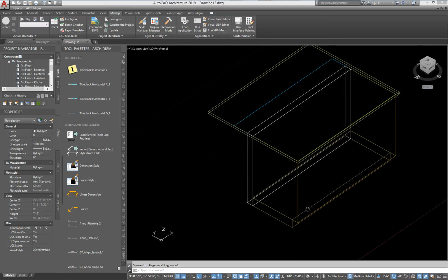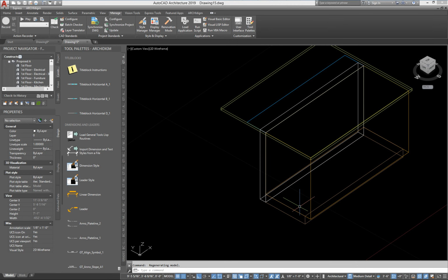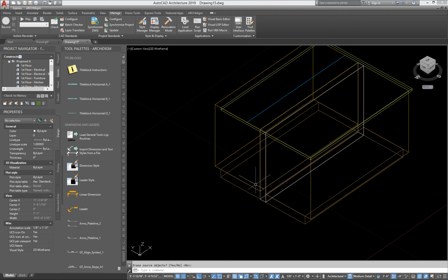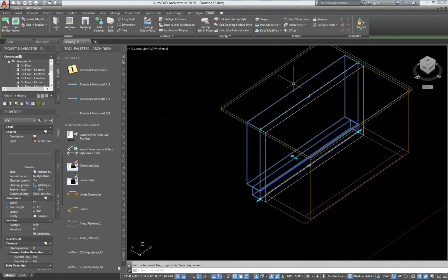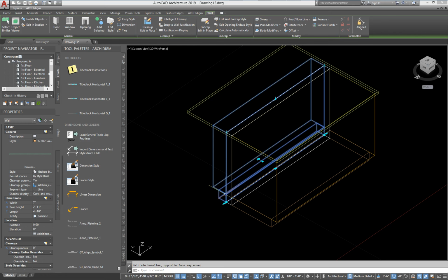And then we will want perhaps cabinetry on the other side. So I'm just going to use the mirror command. I'm going to mirror this cabinetry over to the other side, and I'm going to grab this and pull it back to this body line in the countertop there. So it's a very narrow cabinet. Now I believe the user had like a 12-inch depth. This is coming in at about 7 inches, so kind of a silly cabinet, but let's keep going with what I mocked up here.